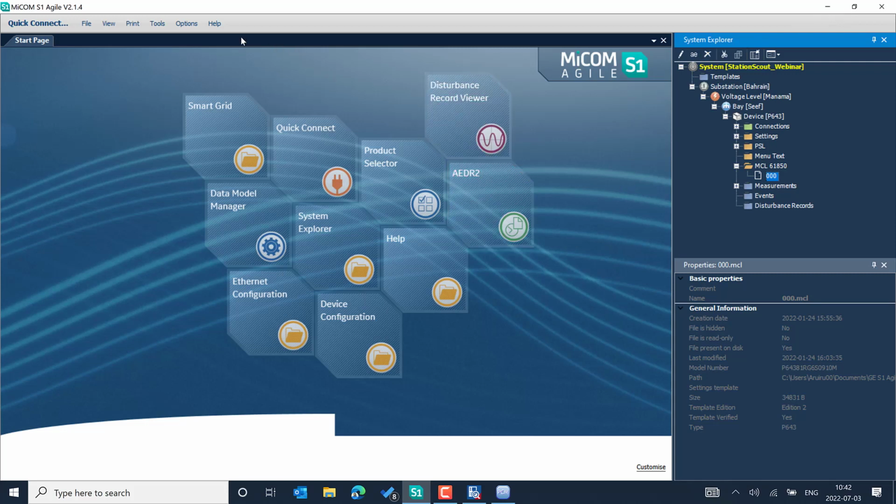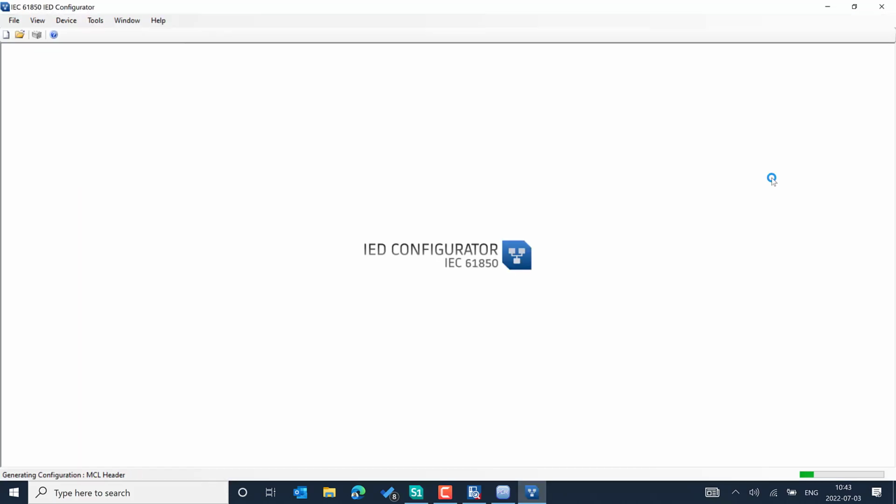And once you download all these host applications, you can separately download the device drivers, IED modules, data modules from the different configuration tools, and you can get the ICD files, and start designing the configuration. And you can even import the ICD file into IED Scout to know the capability with the proper description, so you can get visibility into the different SCL content to learn as a beginner.